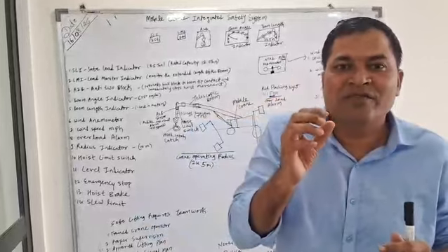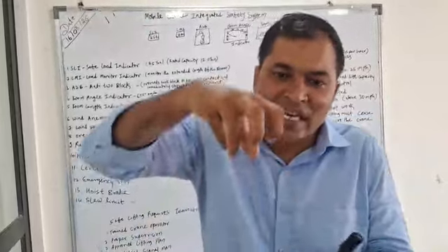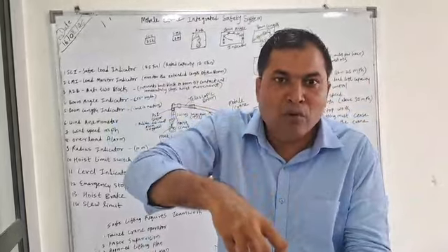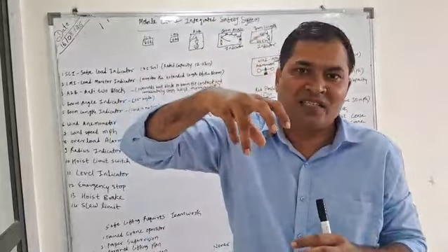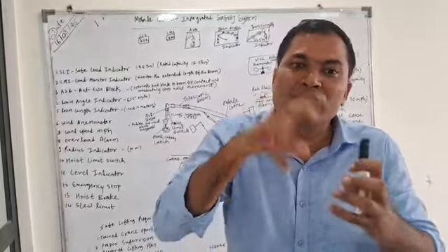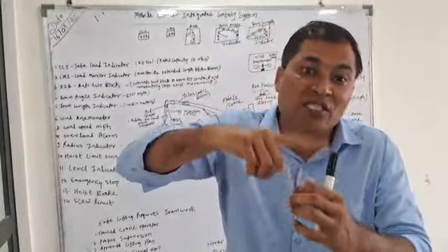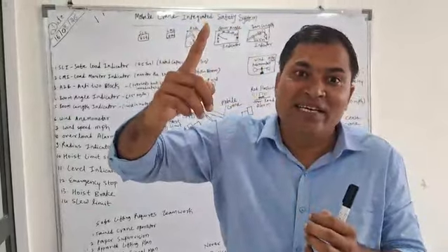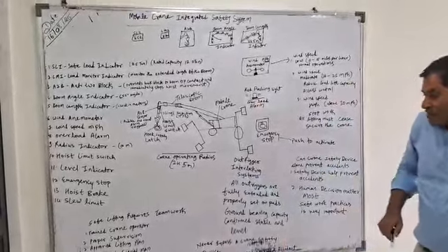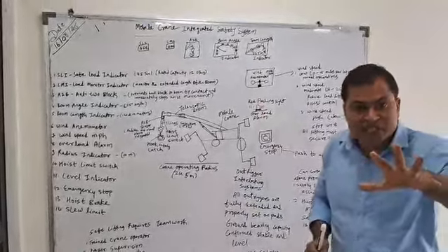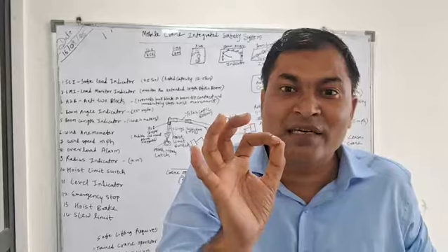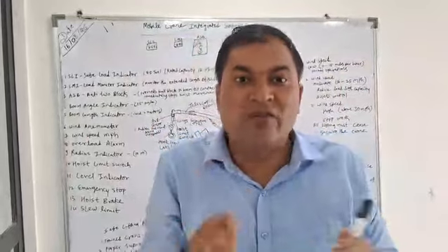Why do you have to keep this much of a gap? Because at the time when the slings go down and want to lift the load from bottom to top, there are jerks as well. Due to those jerks, there is a possibility that the load lifting capacity reaches around 8 ton to 11 ton. So it is clearly mentioned: never bypass the crane safety systems. Never bypass the crane safety system, because the load lifting capacity says 12 ton. That is the whole limit of that crane.